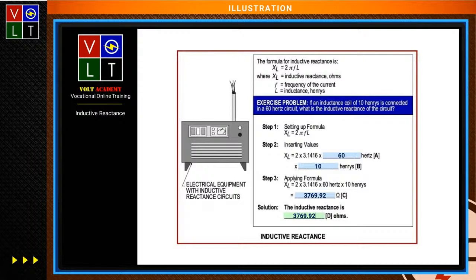Like, they don't want you to have an arc event of 65 AIC. They want to anticipate that ahead of time, and they don't want to wait till that 65K goes to zero point crossing. They want to anticipate that, catch it way before that. And that's why I was talking about the 30-degree phase angle. Yep, trying to explain that.